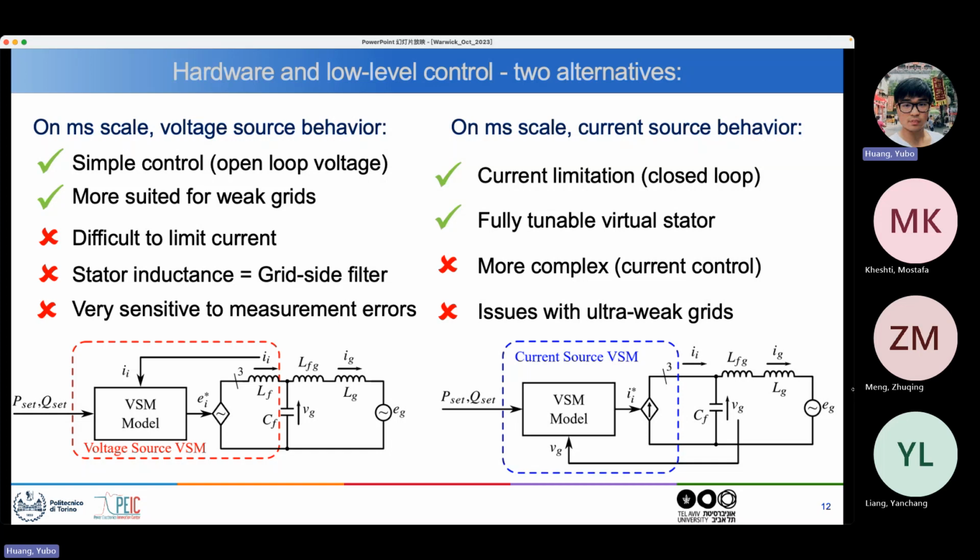And this error voltage divided by the tiny impedance of the output filter of an inverter will give you, for a 10 kilowatt inverter, something like 6 amps of error current. That's impossible. You cannot handle it, and of course that scales with any other power. One possibility to handle this would be to hugely increase the filter inductor of the inverter. That's not practical because inductors are very expensive and very bulky.